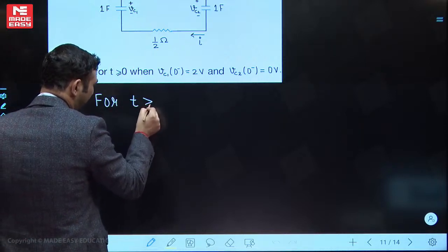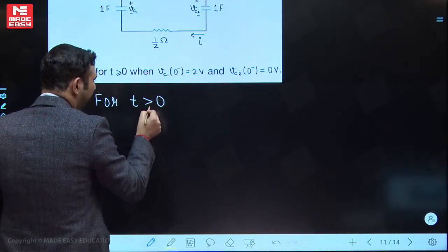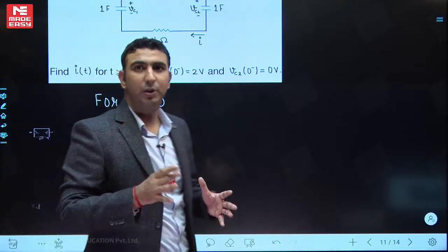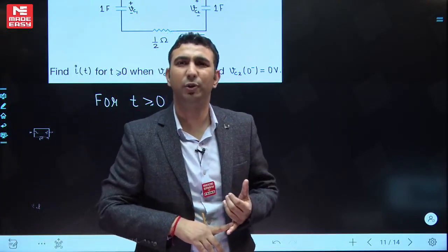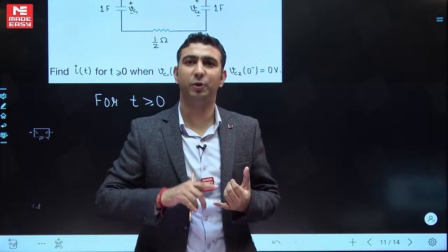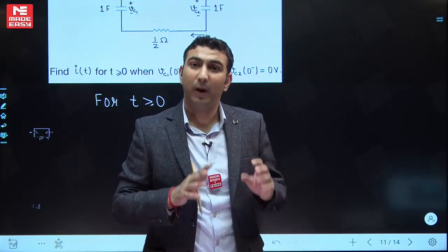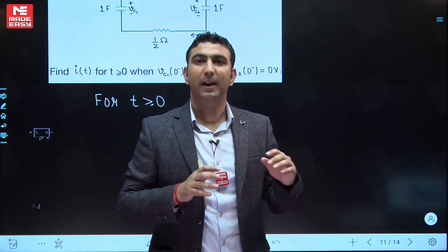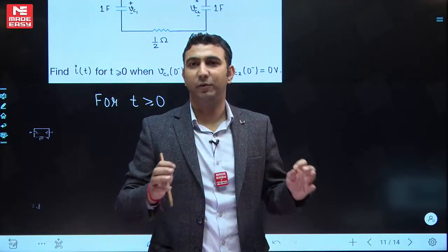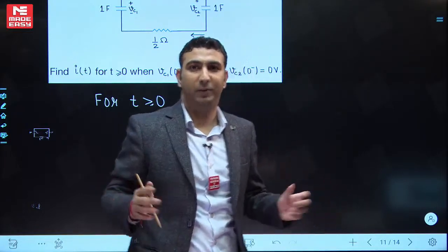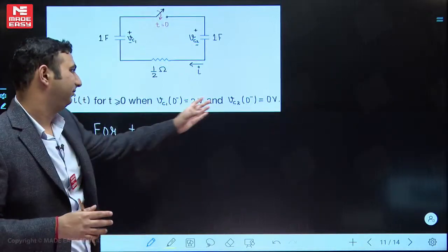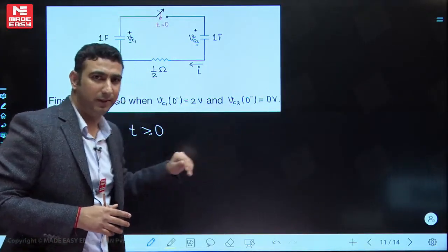because I have specifically told you that for any question on transients, be it an initial condition question, if you are applying the Laplace transform or the shortcut technique, no matter what type of question you are dealing with in transients, you always have to calculate the initial conditions first. There is no escaping from that. If they have given it, fine; if they haven't given that, then you have to calculate it.